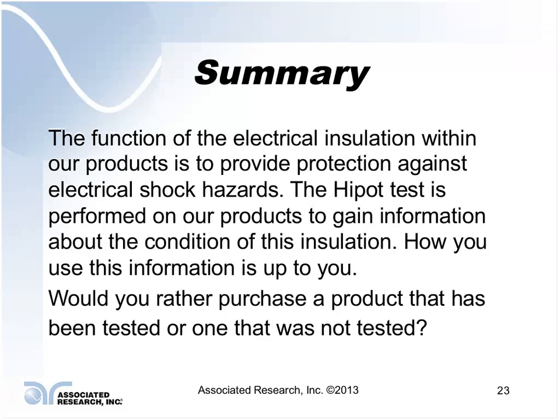The question was, again, is repeated Hipot testing destructive to the insulation? Here, they applied the test potential continuously, 8 hours a day, 5 days a week, and after a week and a half, the insulation failed. He doesn't say in his note what test potential he applied. How does this compare to what would normally be done as a 1-minute test?